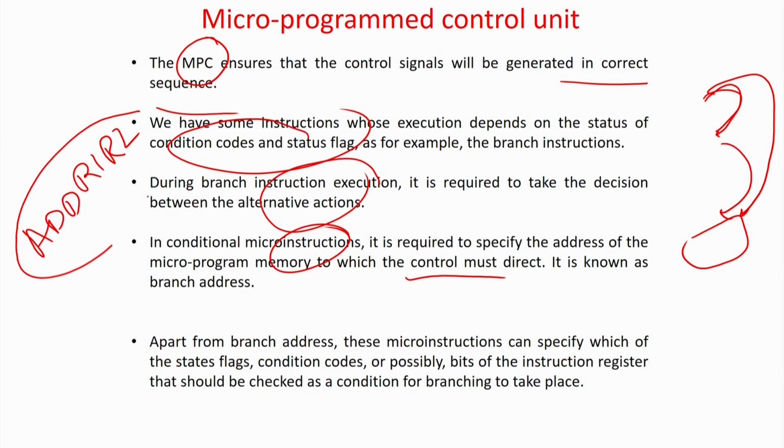it will tell that it is an add instruction which is from register R1 to R2, that is basically a register to register instruction. So the corresponding MPC will start pointing to the microprogram memory address where you have the microprogram corresponding to add R1, R2. When it ends, again other steps will follow. So that is actually the job of a microprogram control unit.